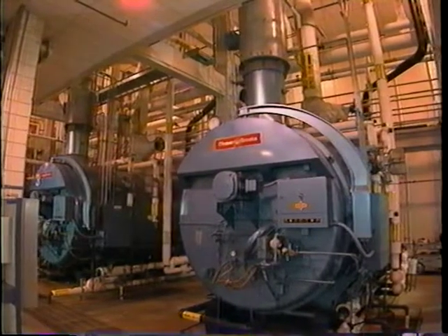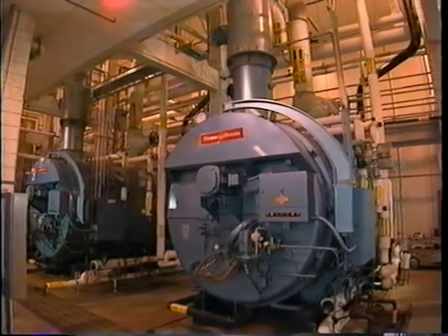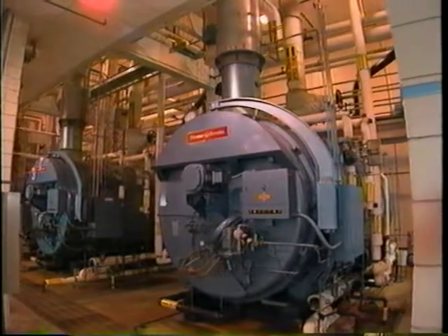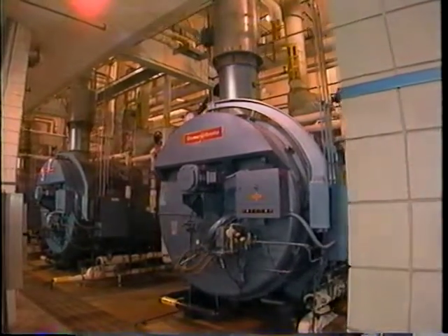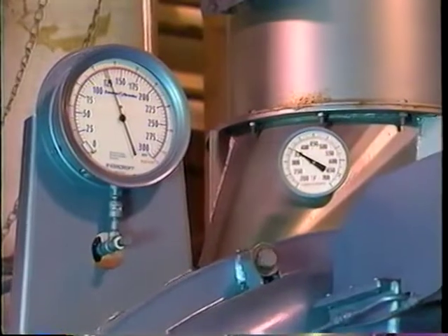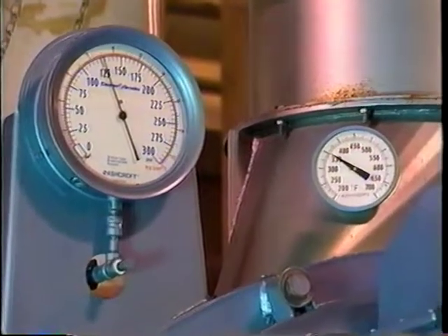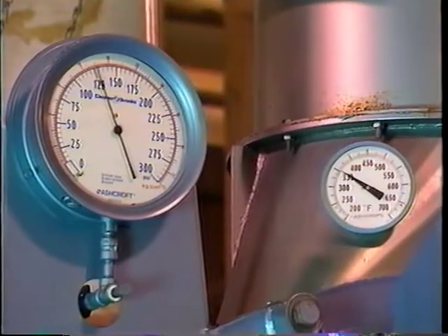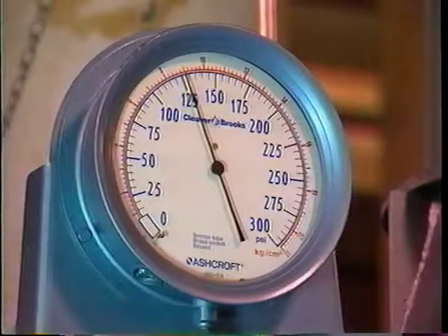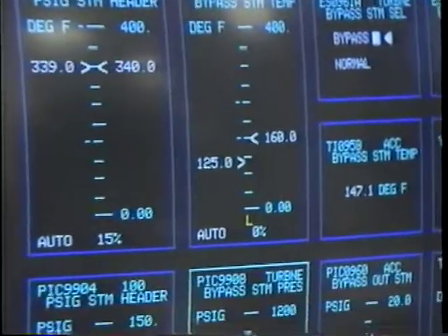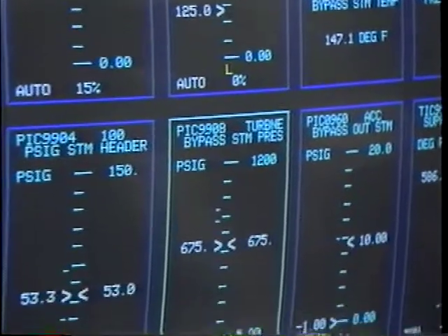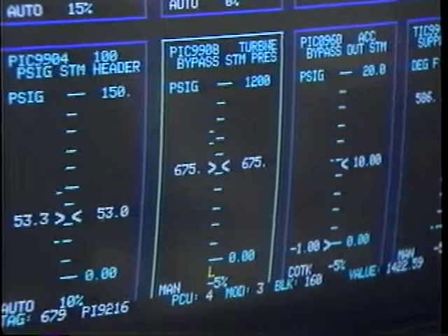Fire tube boilers are used for hot water and low and high pressure steam for heating and process applications. Steam pressure in a fire tube boiler is generally limited to approximately 350 psig and 800 horsepower. PSIG is the pressure indicated on the steam pressure gauge of the operating boiler. If greater pressures and horsepower are required, a water tube boiler is generally used.